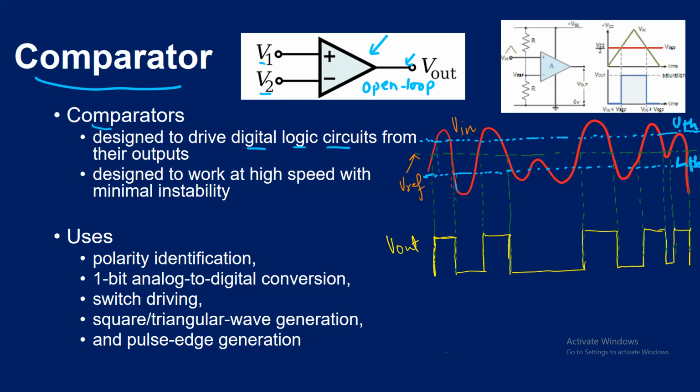For example, you see here the working principle of the comparator. Essentially, any high gain amplifier can be configured as a comparator. You have an amplifier with a gain A. It has a positive input and a negative input. To the positive input, you have a triangular shaped waveform coming in, and to the negative input, you provide a reference. A comparator always compares one input against another input, the reference. The reference can be set to 0 volts as well.